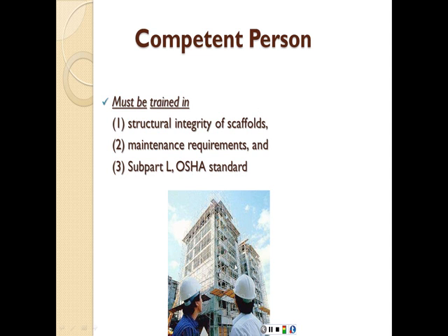In case of scaffolding, the competent person must be trained in structural integrity of scaffolds to make sure that the different components are strong enough, properly connected. Maintenance requirements, if something needs to be replaced or needs to be fixed. And they have to be also trained in Subpart L, which is this particular subpart with the OSHA standards.